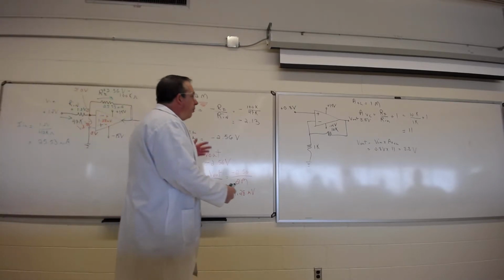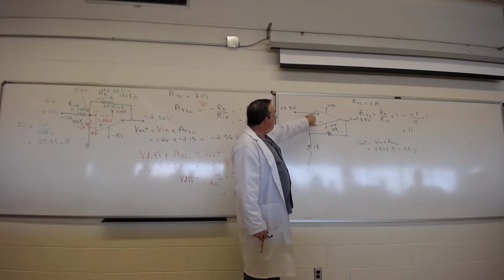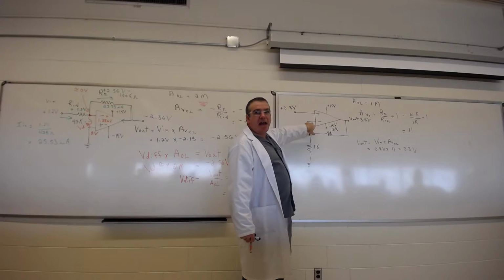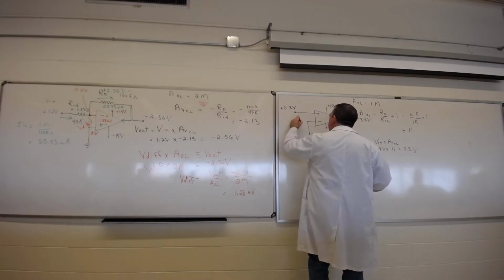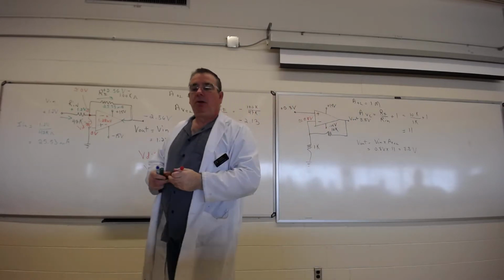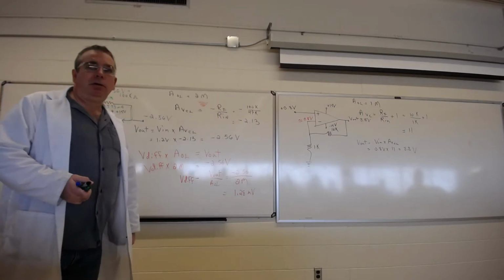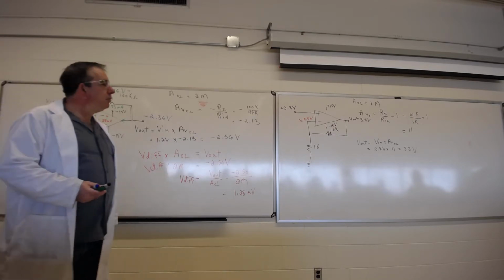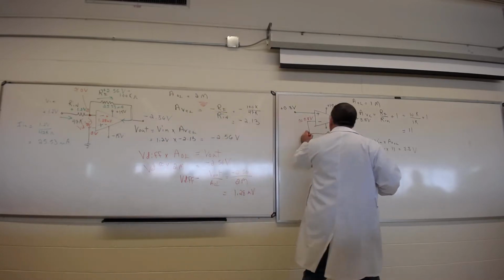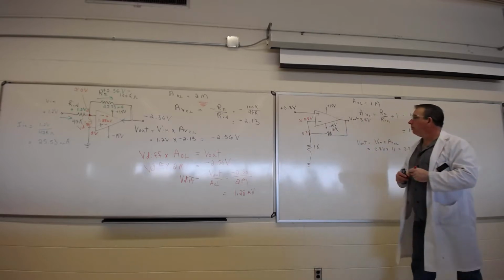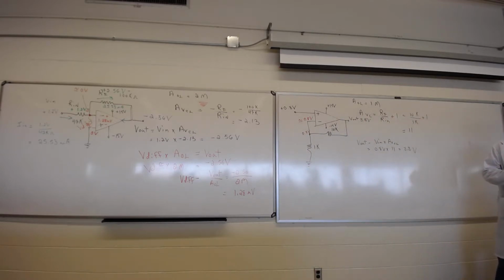So, all right. Back to our op-amp theory. If we've got 0.8 volts on this input, well, because of negative feedback, we should have almost 0.8 volts at the other input. That's what the negative feedback is going to try to force that other input to. So we could put a little note here: this is about 0.8 volts right there. So far, so good?